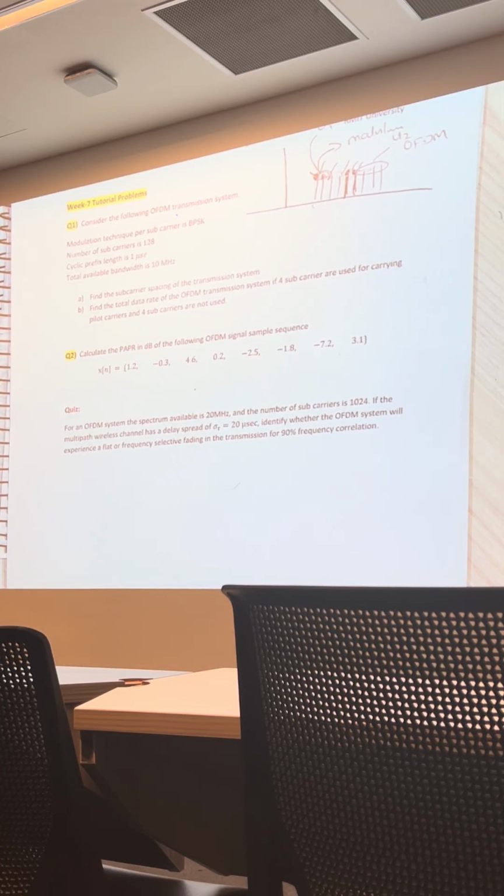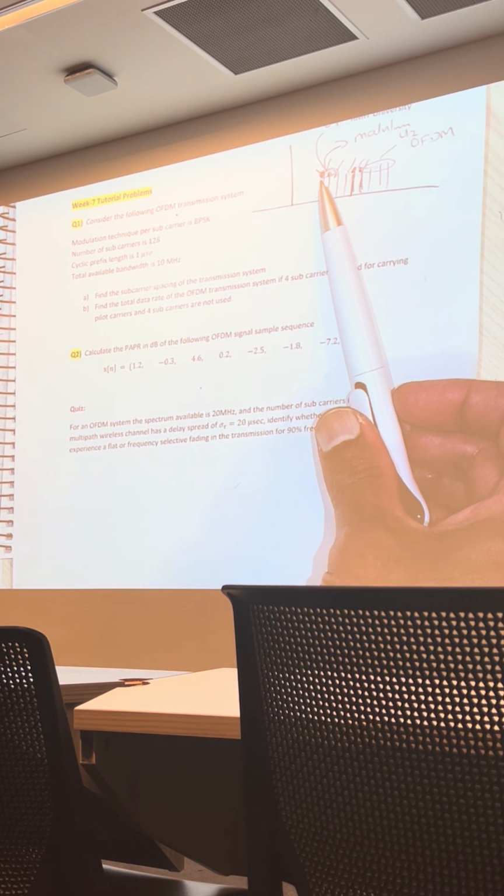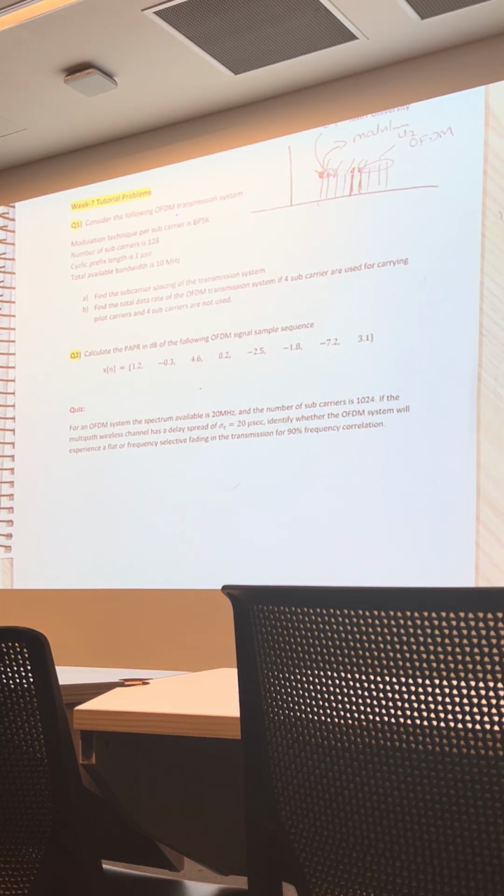It depends whether you're on a $20 subscription or a $150 subscription, the amount of subcarriers that you are assigned. So what does it relate to again? The amount of subcarriers means the download or upload data speeds are quite significantly different. If each subcarrier carries, let's say, 100 kilobits per second, you just multiply that by the number of subcarriers in a linear way, if the same modulation technique is used.